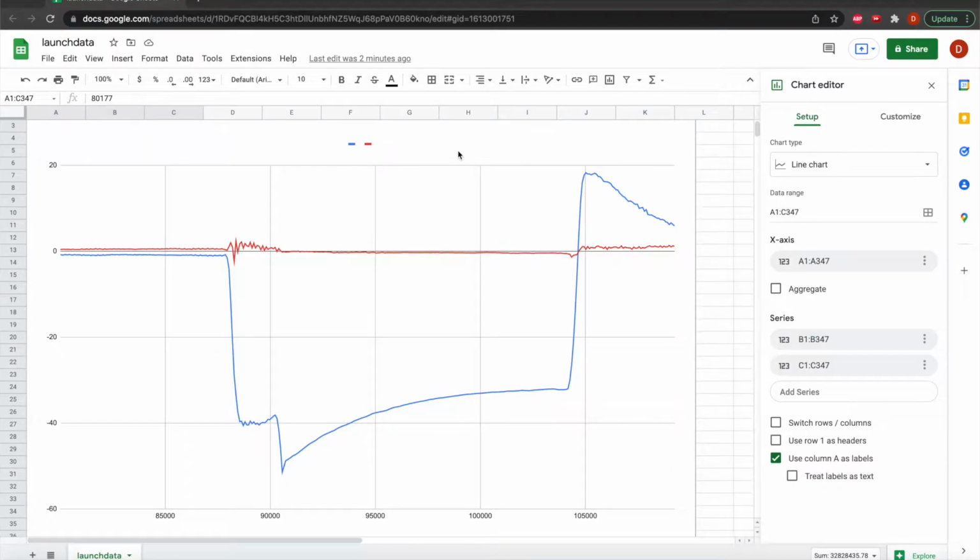That was fun, so let's take a look at the flight data. Alright, so I've imported the flight data into an Excel sheet, and it's important to note that during the flight I actually only thrust vectored on the pitch axis because the roll axis servo was not working properly, so I locked that in and turned it off because it's dangerous to launch if it's not working correctly.